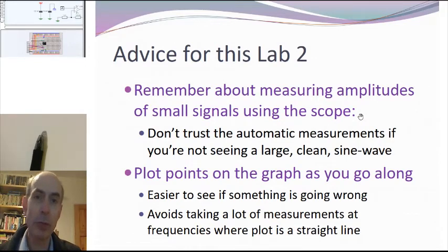And the easiest way to do that is to take two outputs from the function generator. Either use both channels and set them to the same frequency, or use a BNC T-piece which splits off one output so you can take two BNC cables away from it. Take one to the input of your op-amp circuit and take the other one to channel 2 of the scope. Once you've got a nice trigger, you can turn on averaging. That will help to reduce the noise.